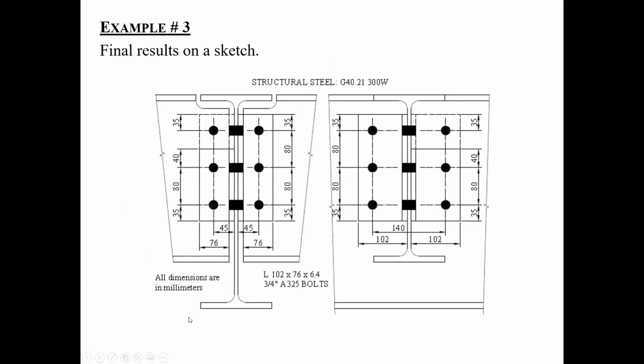I got that at the very beginning, so I'm okay for the thickness of the web. In other words, that means I'll have sufficient bearing. And now your final sketch. So here you go. So now you'll notice here. I like this example, and I'm giving you this more for your general information, guys. You're going to have one or the other two problems on the test, not this one. But here what I want to show you is that, remember the other example, the very first one, we coped the beam down here? Well, in this one, you would cope the beam up here, and the cope would make sure that you can butt this beam into this connection so that it doesn't interfere here.